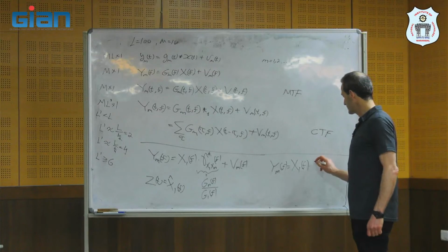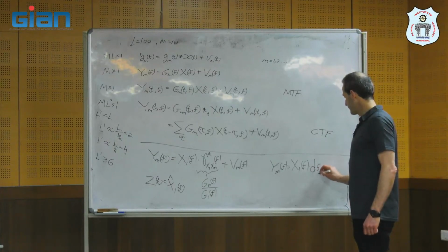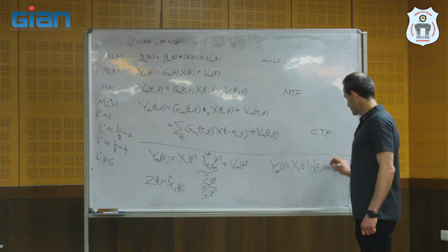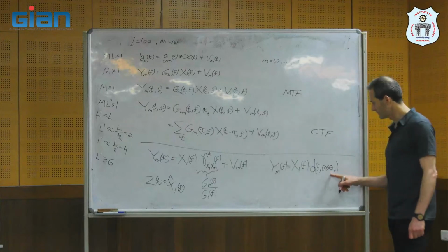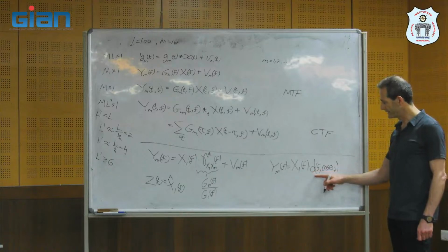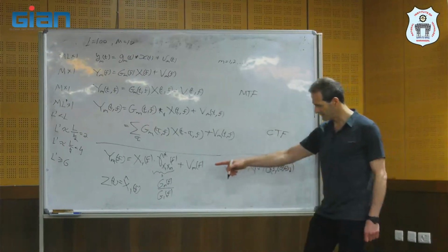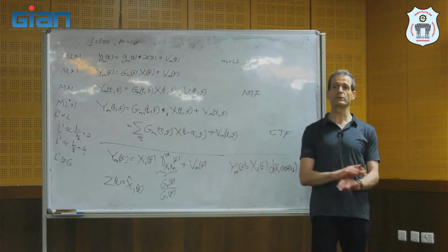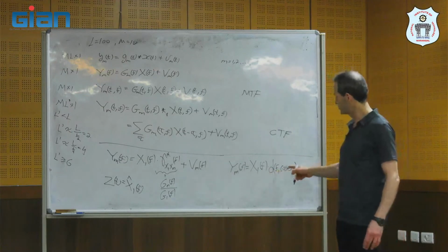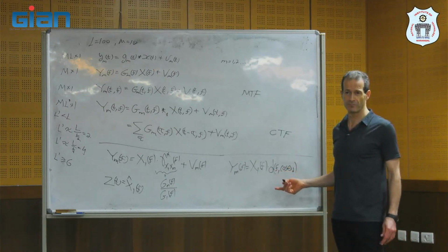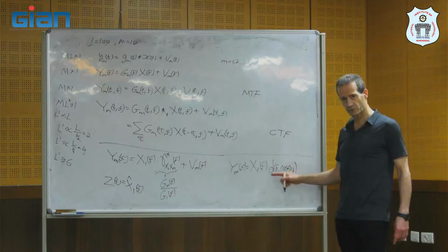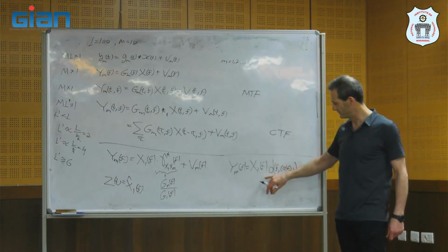So it can be written like this, d(f, cosine theta_d). So theta_d will be the direction of the desired source, and this will be something similar to the relative transfer function when we don't have reflections. It's just an exponent. It corresponds to delay, because if you have a sensor delay when you transform into the frequency domain, it's just a phase difference.